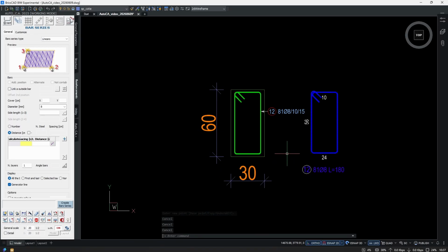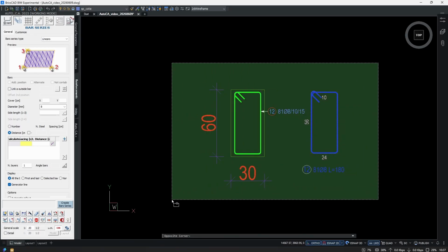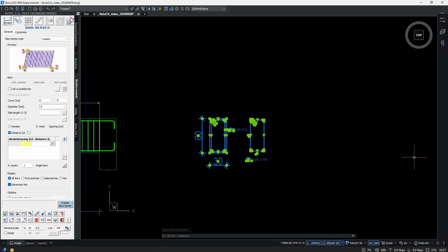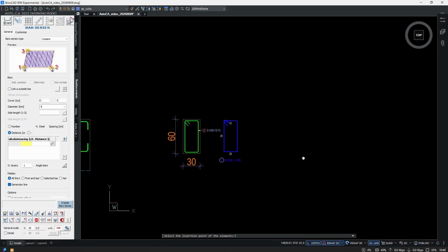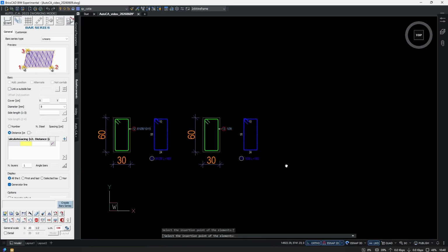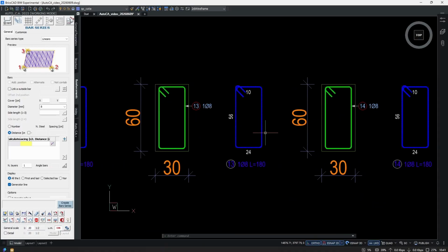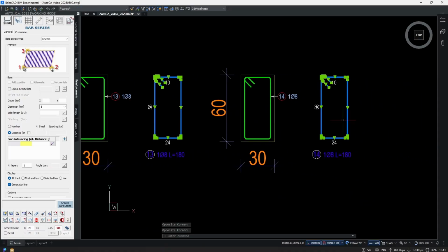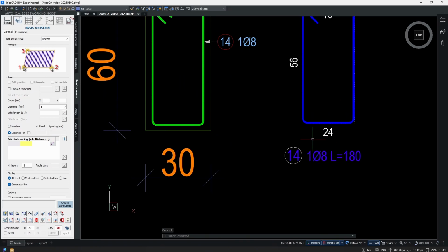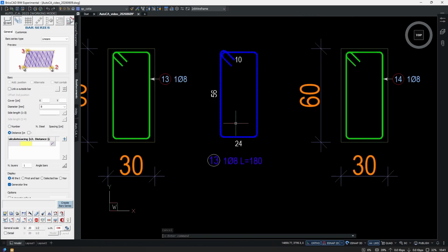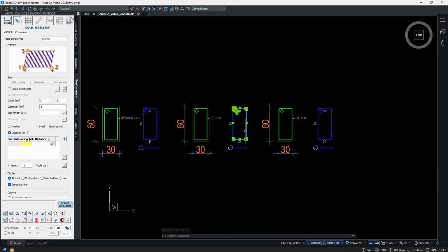If we want to copy this whole structure to have multiple cross sections, we will tumble into a new problem. So I'm gonna create 2 more cross sections. But now our new outside stirrups have only 1 bar connected to them. So they are counting only themselves.